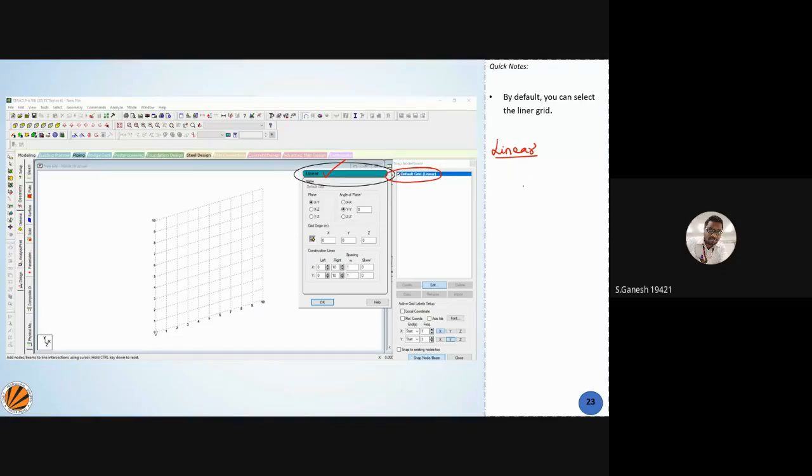It can take x, y, or x, z, or y, z, so it is a kind of two-axis plane. You also set the plane angle, which angle you want to work with. You can tilt 30 degrees or 45 degrees, so you can tilt your plane angle about x, y, or z.